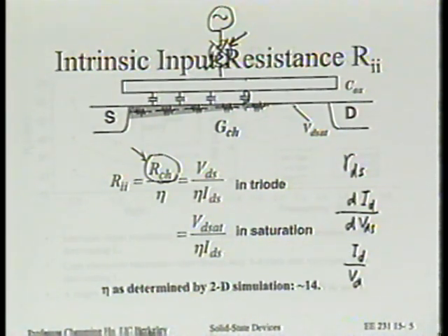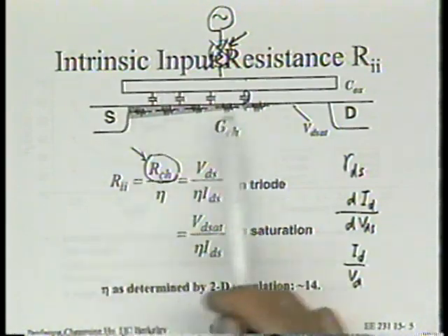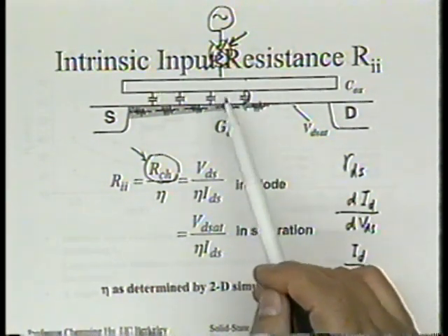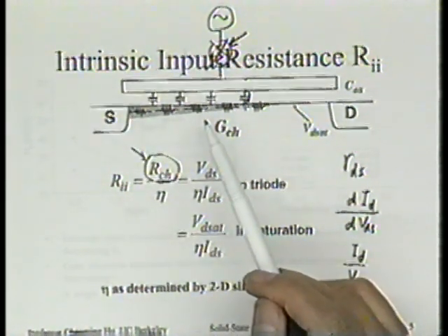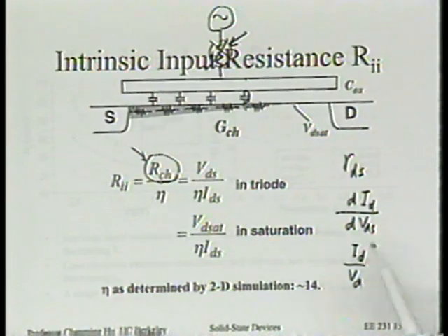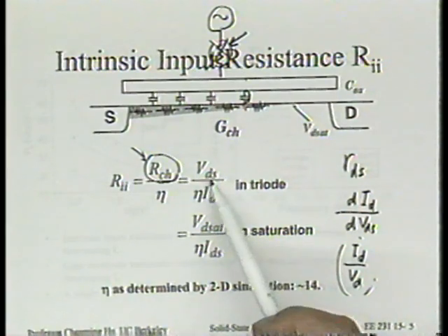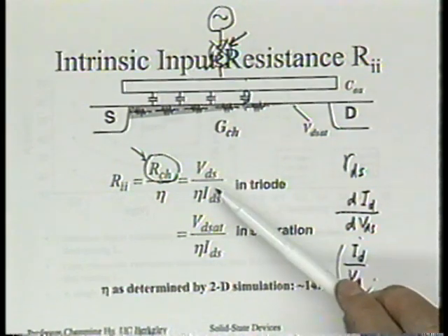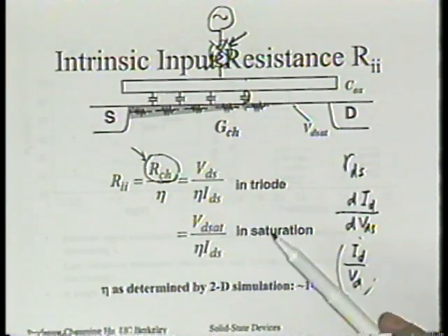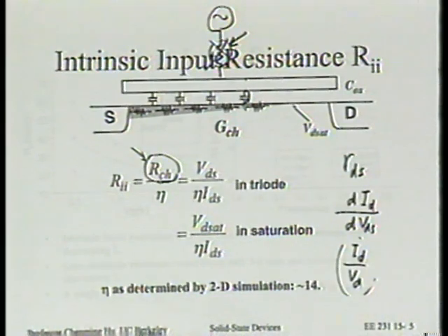When you think about that, it turns out that because we're just talking about resistance, and the reason we need this resistance is that when the current flows through this, it's going to have some IR drop, the resistance we're talking about truly is VD over ID, I'm sorry, not ID over VD. It's really just VDS over IDS. And this is really nice because SPICE already models IDS very well, within 2%. So we can model this very nicely. So no additional modeling to do.